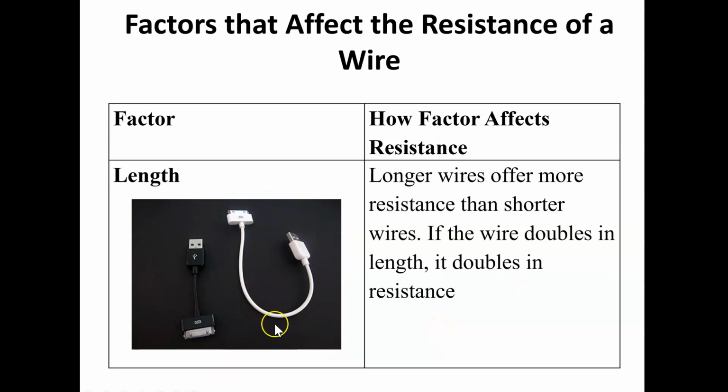The length is another factor. So the longer the wire, the more resistance it offers compared to shorter wires. If the wire doubles in length, basically the resistance is also doubled, which also makes sense.